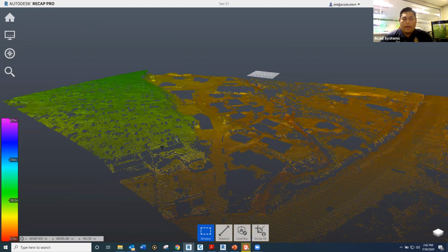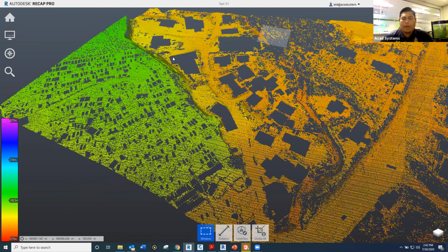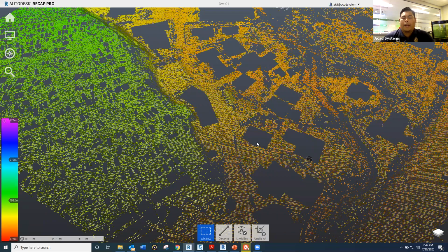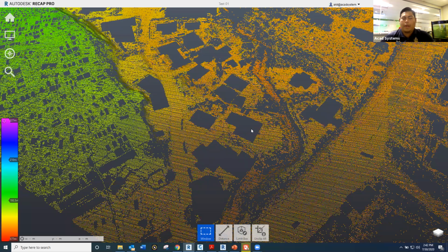Okay, and we are so lucky today because all the unneeded points are already processed and taken out by the surveyor. And next, if you really need the points from this empty area, you will go with your total stations, manually go to site and measure these points exactly, or you can just create a graded model in Civil 3D later on.